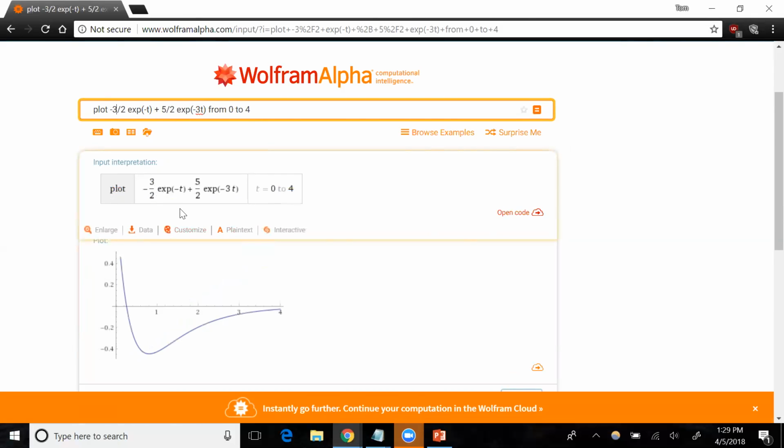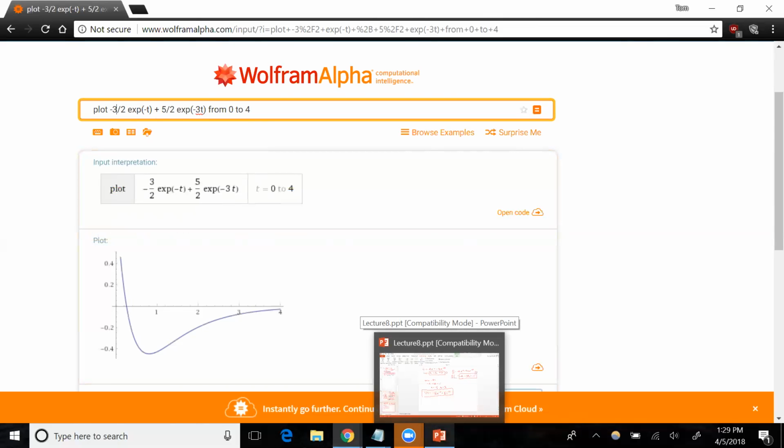We could also arrange these things so that the initial slope is 0. We can find a solution that will have the initial slope of 0. Anyway, this is a digression, but there are 2 degrees of freedom basically in the solution for a second order circuit, and you need 2 initial conditions to pin those degrees of freedom down.